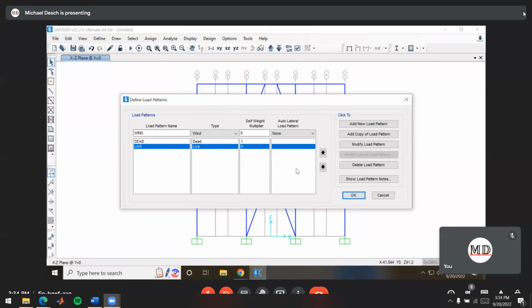patterns there. Why does it do this? Well, normally when you're designing a structure, you've got wind, and it's not only coming from a single direction. So you have to analyze it for wind coming in all these different directions. That tool goes and makes all those different types of wind loads automatically. However, for this one, we only want the one wind load. So we'll do this. It should say wind, wind, 0, none. Then we'll add it to our load pattern, and it should look like this.